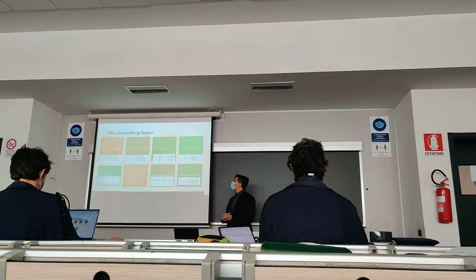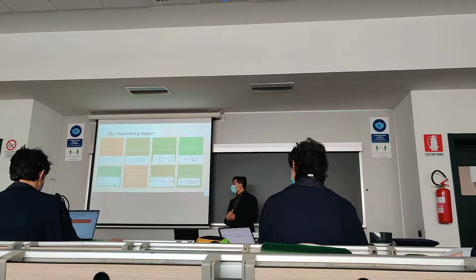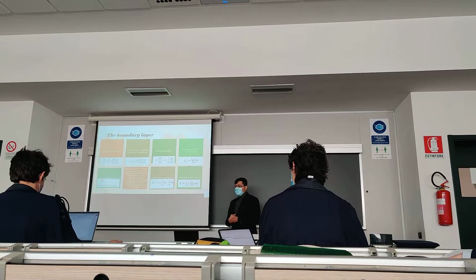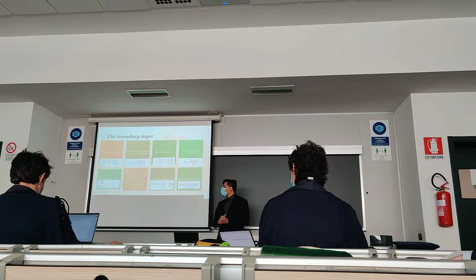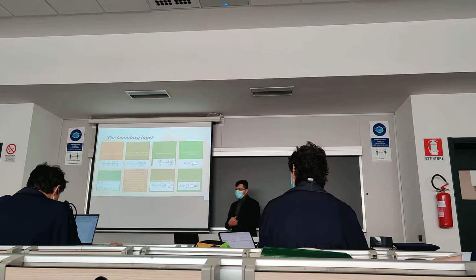It is the pressure recovery coefficient at normal conditions to that of the ideal conditions. The ideal conditions is where the maximum coefficient of performance is achieved with a particular area expansion ratio. So that is the ideal case. And so the Cp has a correlation with the area ratio: 1 minus 1 by area ratio squared.